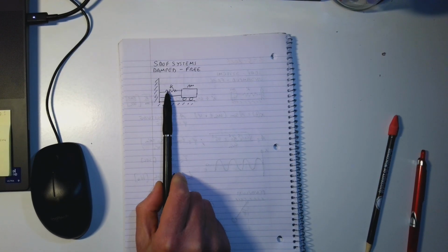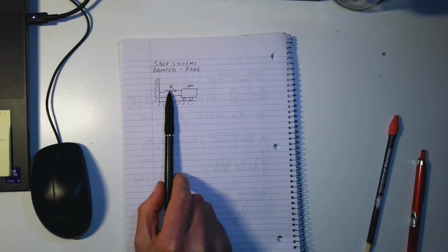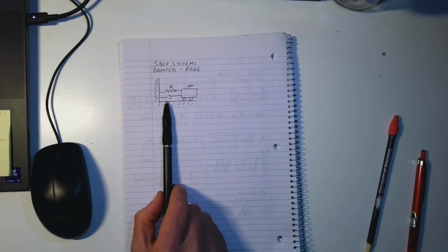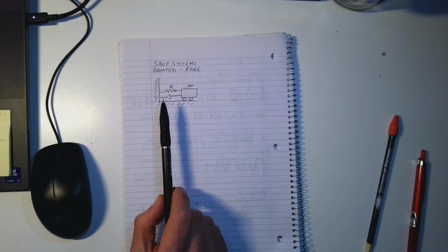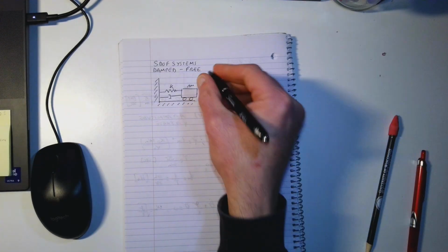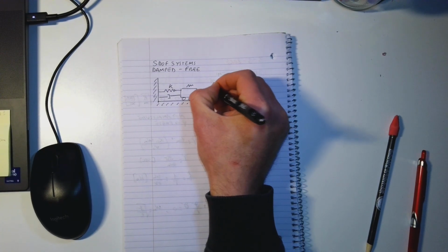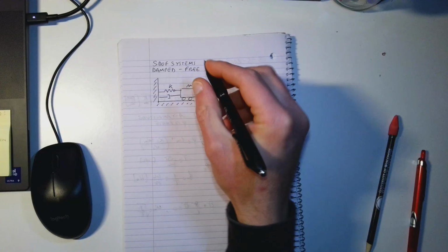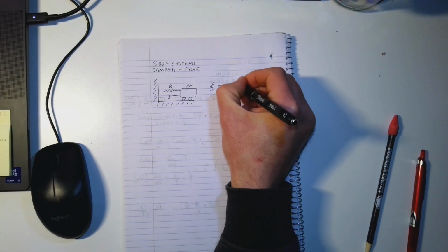Exactly like before, the force that comes from the spring depends on the elastic constant of the spring and the displacement. The force that comes from the dashpot depends on the coefficient of the dashpot, and it depends on the velocity of the object. So we can write Fc, which is, let's say, the force from the dashpot, as the product between c, which is the constant, and x dot of t.